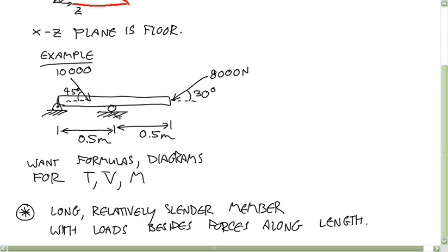Okay? Then once we have those external loads, we identify the important points, make one cut, draw the free body diagram, use Newton's second law, rotational Newton's second law, get the formulas, go on to the second cut, and so on. Okay? So step one, or I guess I probably numbered those steps before. I know I have a bad habit of giving you a nice numbered set of steps and then using different numbers when I talk about it again.